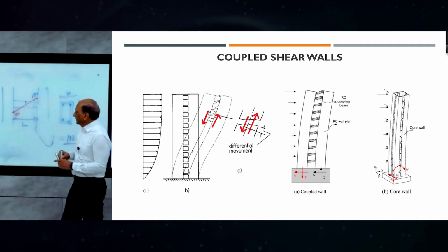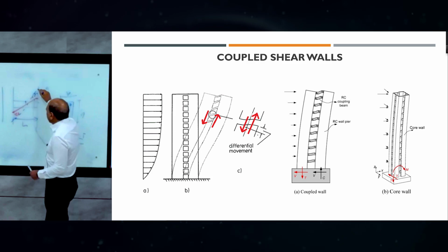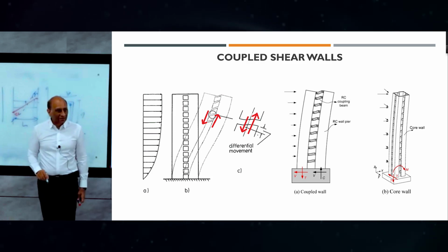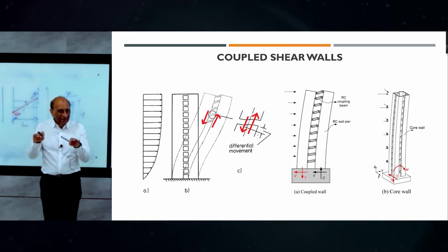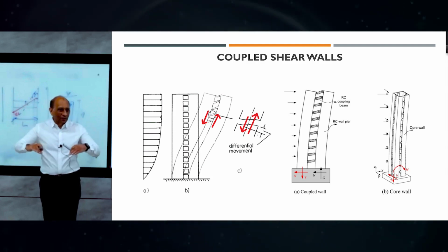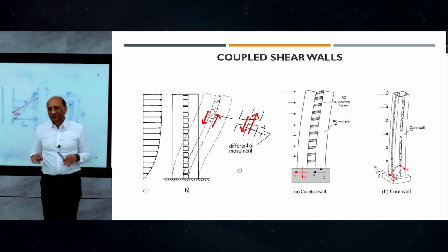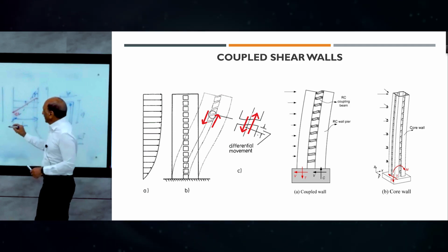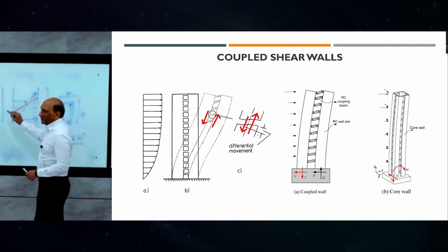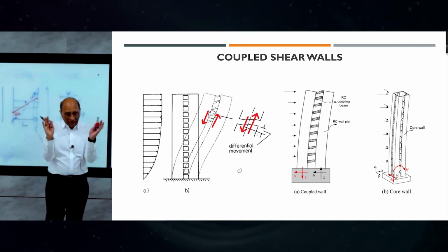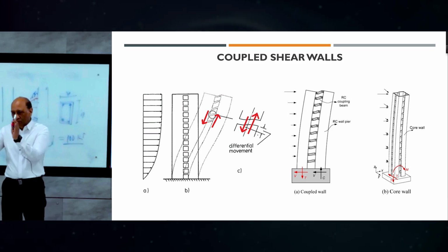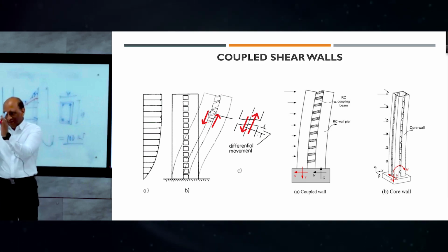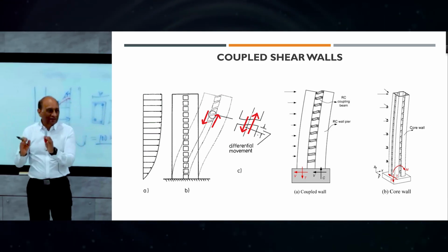And then any moment above that, if it comes like this, it will not exist because the reinforcement that you put is based on 120. So it will yield and come back to 120. And then the shear will not break. So which means below 120, it will behave like an elastic beam. It will try to hold the walls together. After 120, it will just let them go, holding 120 always and not breaking.